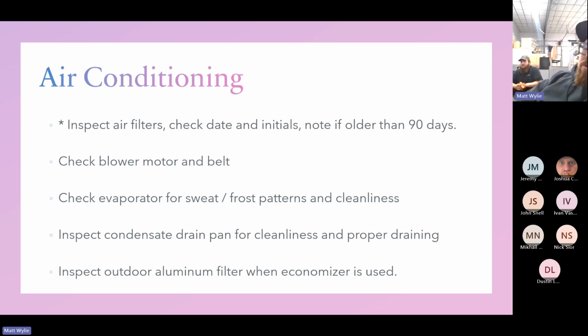Hey Dustin, do you remember, is the pulley inward higher amps? Or is it out? Do you remember? I think if you open it up more, it decreases the distance around and I think lowers amp draw. Yeah. If you twist it in, it tightens it up and stretches it out and increases the amp draw, the amount of distance it has to travel.